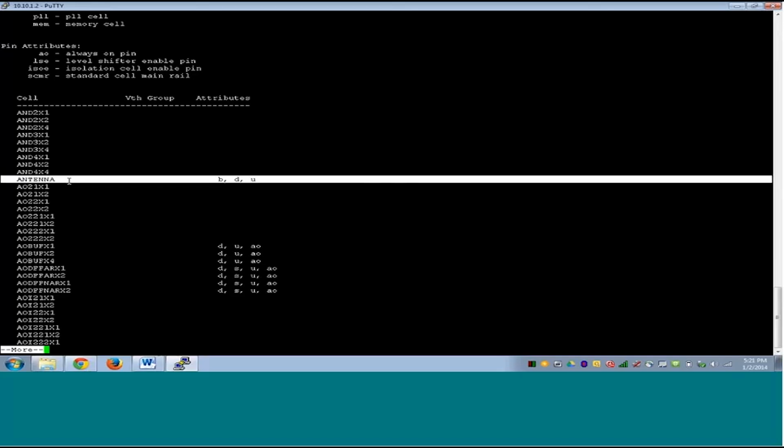Now, a standard cell library contains all kinds of cells. It contains all the combinations, sequential, special cells such as antenna. But should antenna be used in synthesis? No. It is a cell that might be used by the layout engineer to resolve some problems which are very specific to layout.